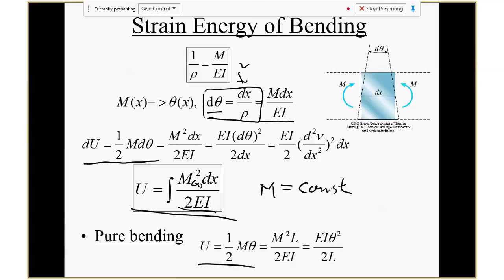And again, why do we need to know the energy? What's the use of this strain energy? It's related to potential. It's the energy stored in the beam, and you can use this equation later on to do analysis. For example, for numerical simulation, numerical analysis, finite element, you're going to use energy. One approach is using the energy equation to get the deformation.